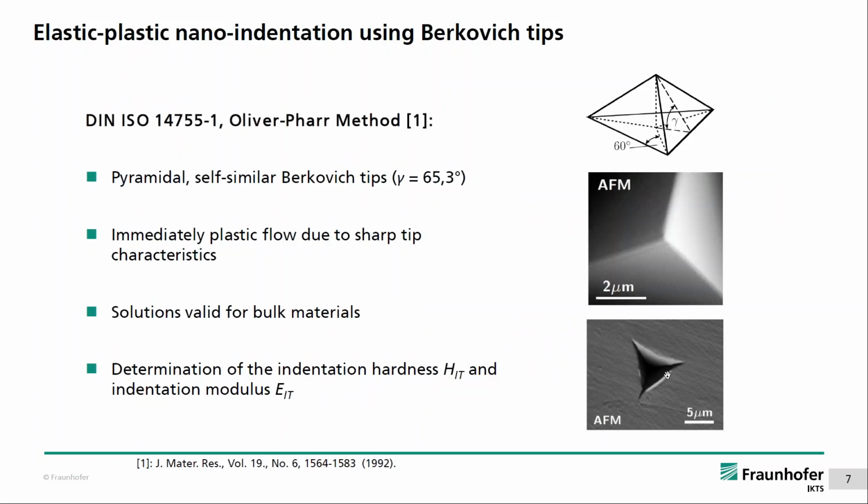So these are the experiments you've seen before, just an imprint, and this is an AFM scan of such a Berkovich tip, and this is a sketch, a drawing of the Berkovich tip. And when you have this force displacement curve with these sharp tips, with a pointed tip, you always get immediately plastic flow because they are very sharp, and you always have plastic flow in the material.